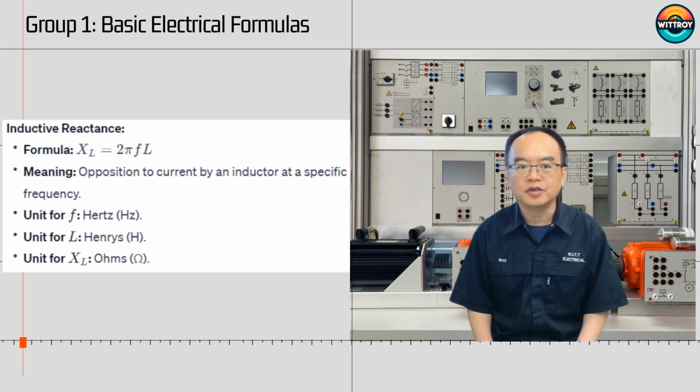Additionally, inductors can also be used in DC circuits for energy storage, storing energy in a magnetic field, useful in DC-DC converters. Chokes, blocking high-frequency AC signals while allowing DC to pass. EMI suppression, filtering out high-frequency noise from power and signal lines.